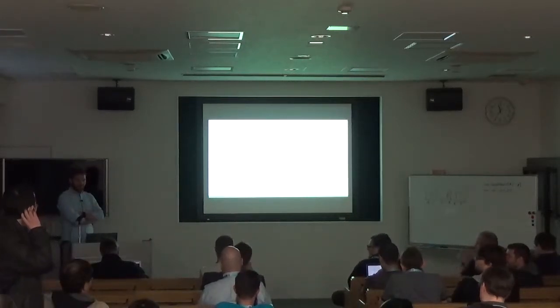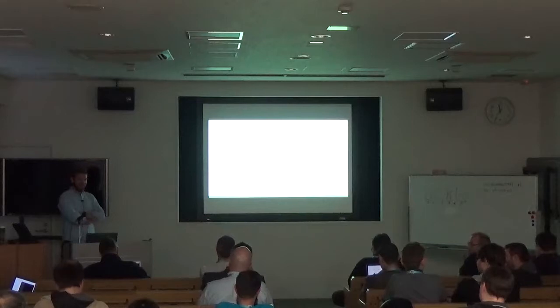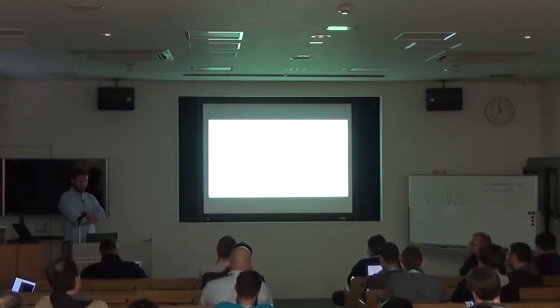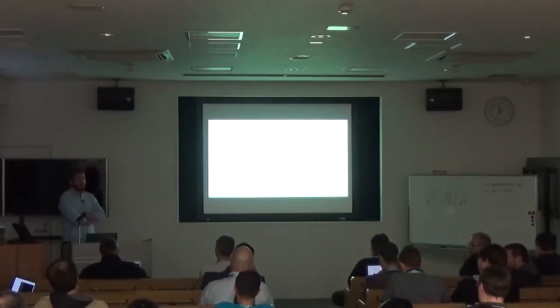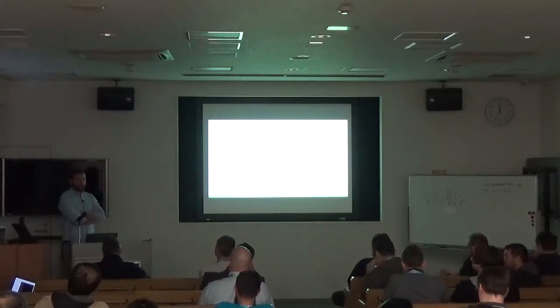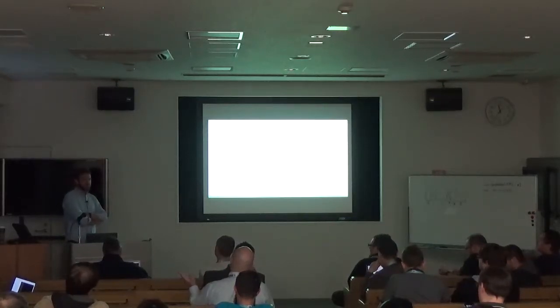Sorry, I got the microphone. So the lwIP idea isn't a bad idea, but you realize you can't allocate memory. Right, so that's the issue. Many embedded operating system TCP/IP stacks are cheap copies of the BSD TCP stack. Have you considered looking at some of those and doing what they did to our stack, instead of pulling in something as large as lwIP? You basically can't have timers, you can't have endless allocations.